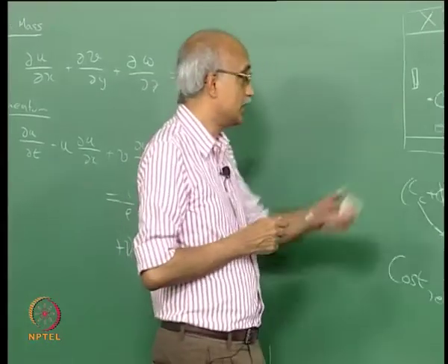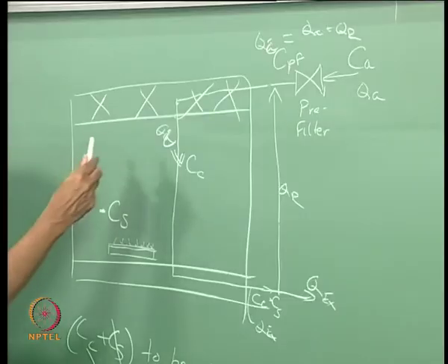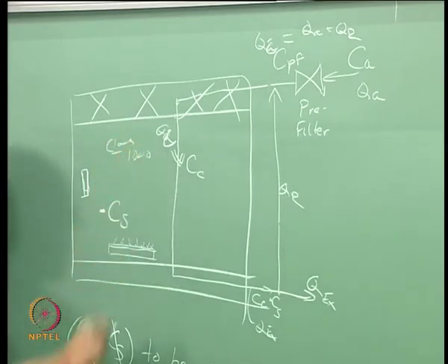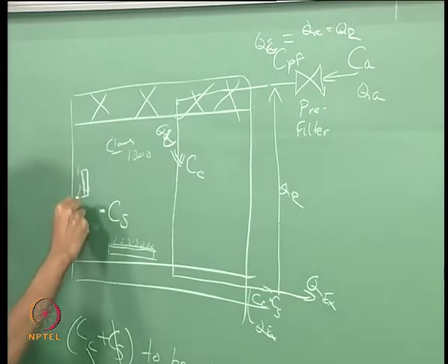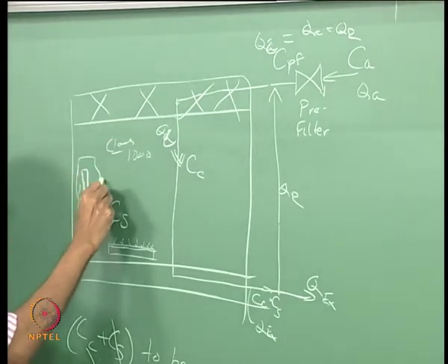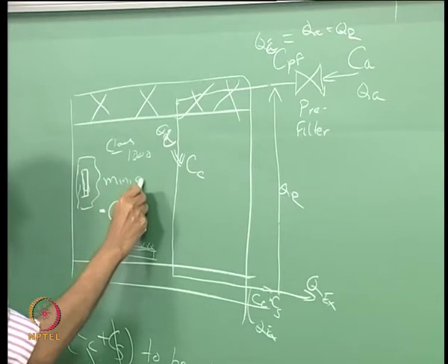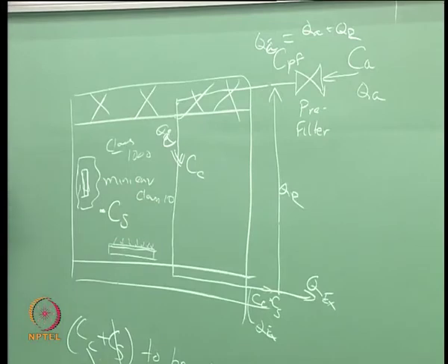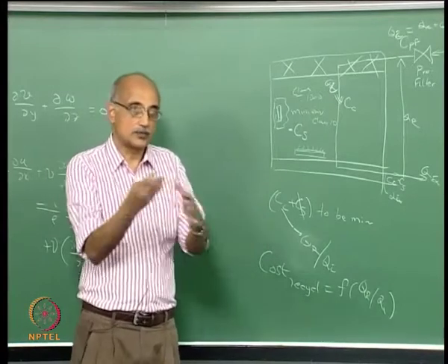For example, in this clean room, the entire clean room may be a class 1000, which, as you know, is pretty dirty, right? But around the product, you can actually design a mini environment which is a class 10. So, it's 100 times cleaner, and you make sure that you never take that product out of this mini environment.